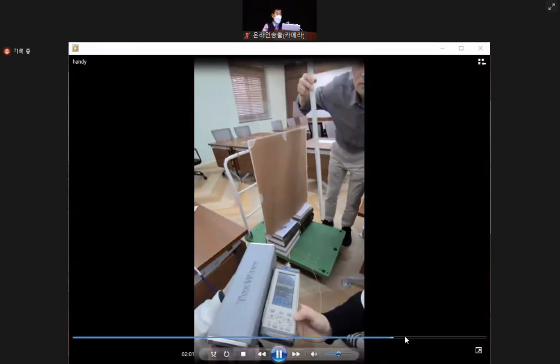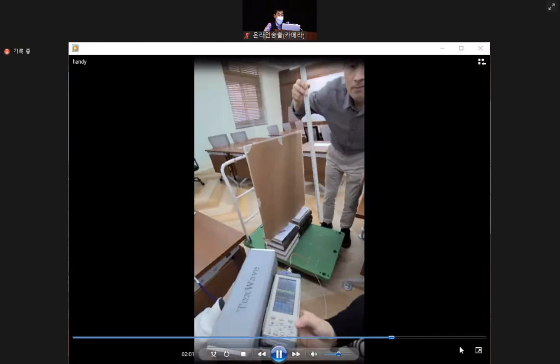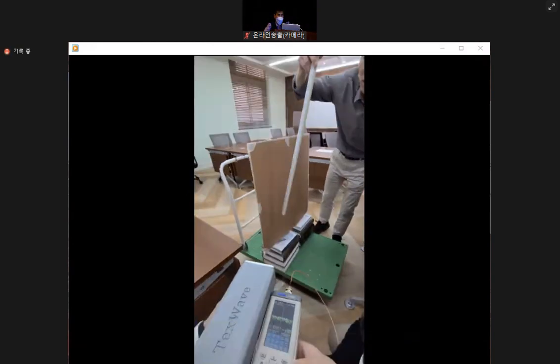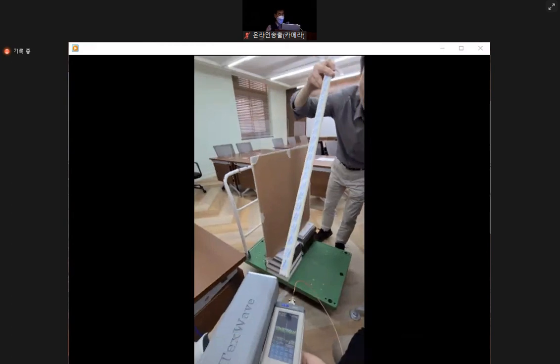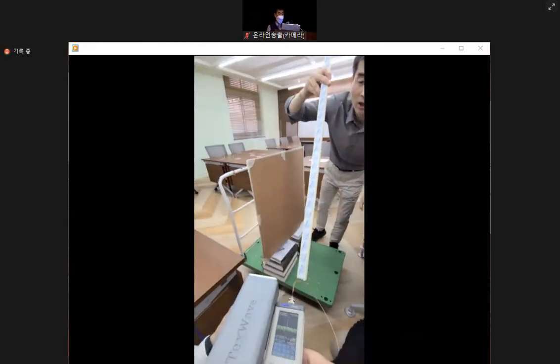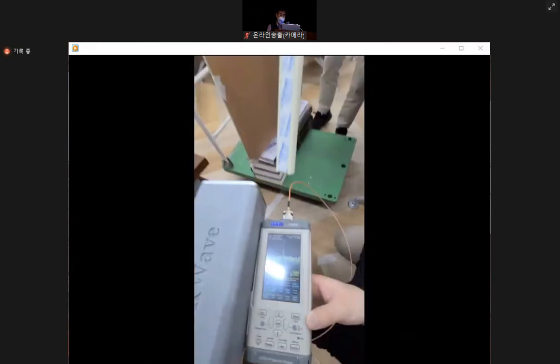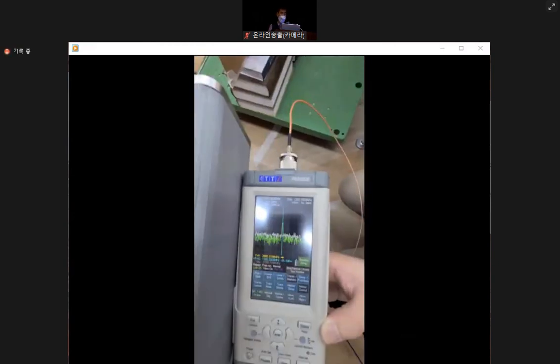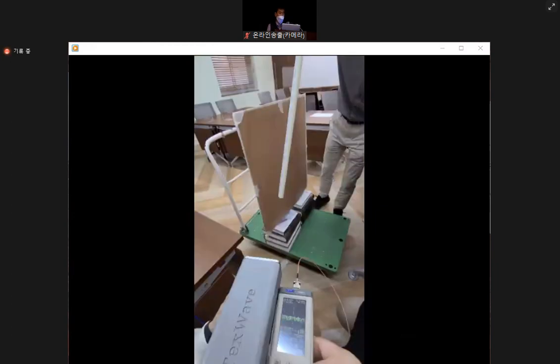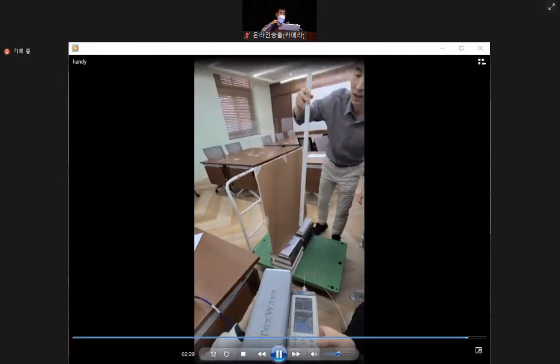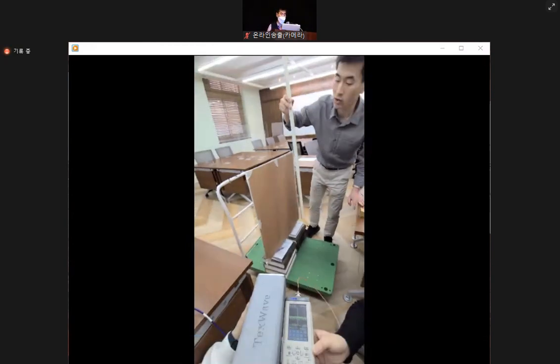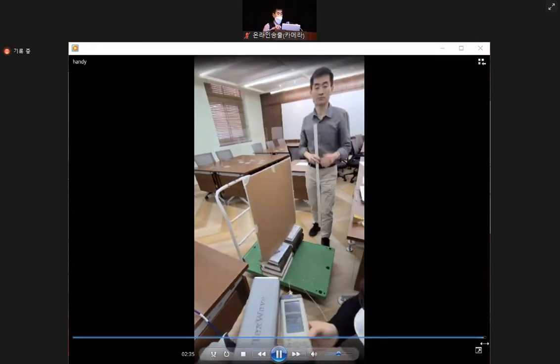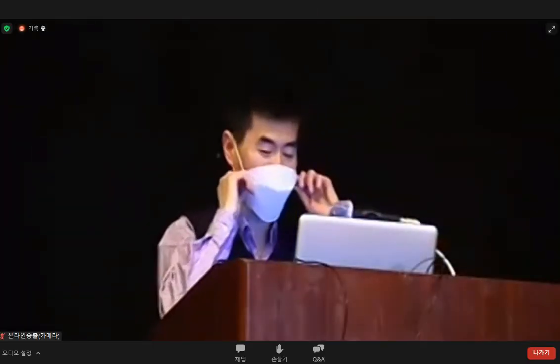Now it is about minus 43. With the handheld probe at 80 degrees or 90 degrees, it is quite compatible and gives a consistent result for the analysis. The value goes down. I mean, the values obtained by the stationary probe and the handheld probe might be a little different because there must be some kind of offset in the referencing, such as calibration, but the trend is exactly the same if you change the angular position and the distance in the cylindrical coordinates to test that.